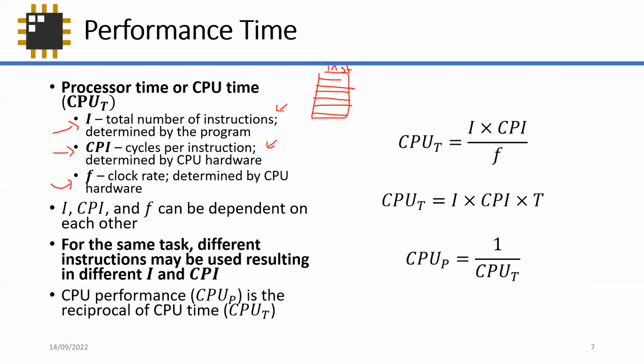Okay, and those instructions are processed by the CPU. But when you plug it into your CPU, the best CPU hardware out there processes instructions with a cycles per instruction equal to 1. That means for every single clock cycle, from end to end, it processes one instruction at a time. However, not all CPUs do this. The best do. Low power CPUs, embedded processors, maybe not so much. It really depends on the design.